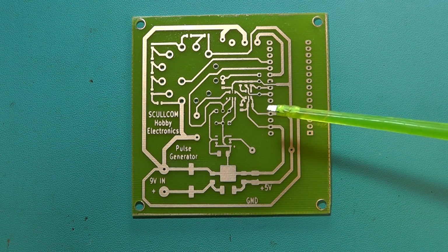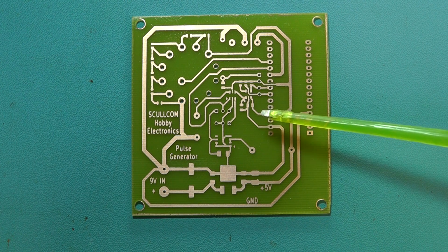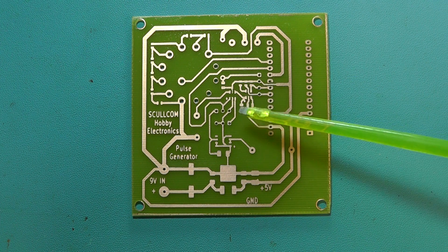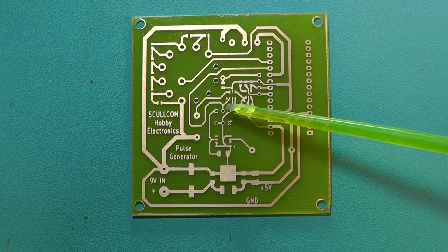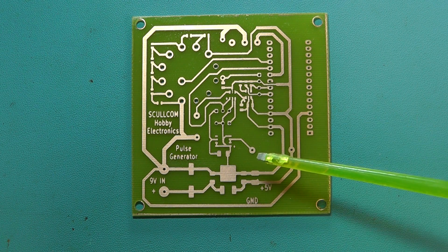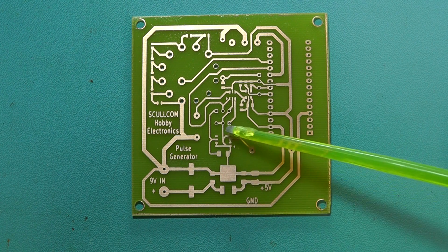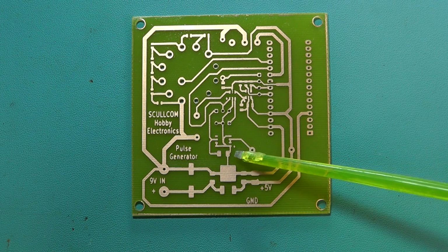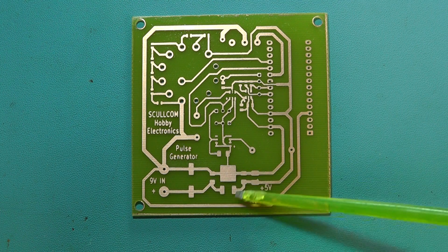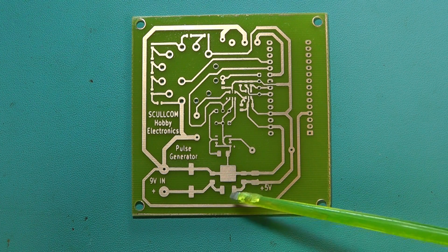The two small ICs we're using are TSOP 23 6-pin packages, very small, and they're in this location of the board, and I've indicated on the board pin 1 of those ICs with a small dot, as you can see there and there. The other surface mount IC we're using is a slightly larger surface mount component, and that's mounted here on the board. Again, I've indicated pin 1 with a small dot there, and this area here is the surface mount IC for the 5-volt regulator that we're using on today's project.